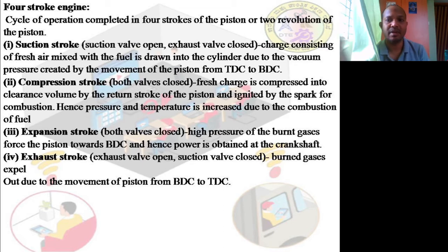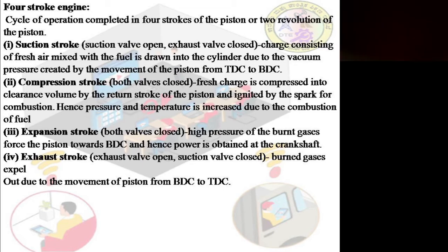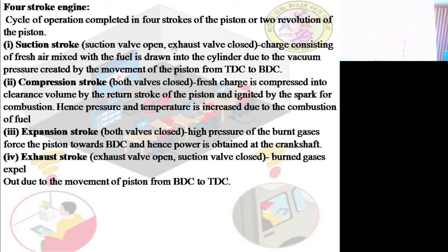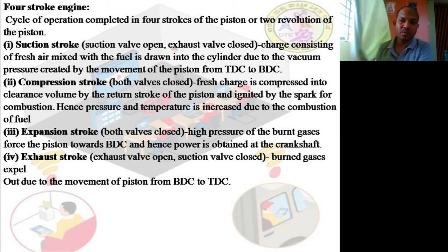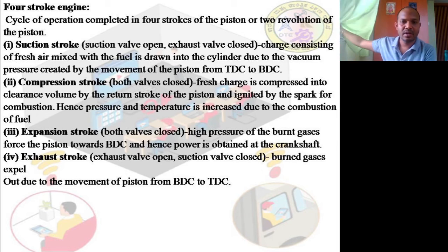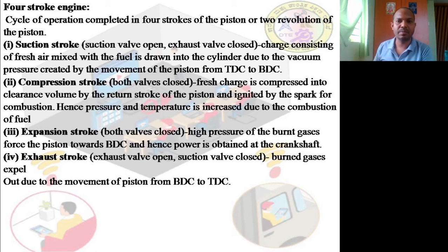Now, in the expansion stroke, both valves are closed and the high pressure of the burnt gases forces the piston to move from the TDC towards the BDC, and hence the power is obtained in the crankshaft.